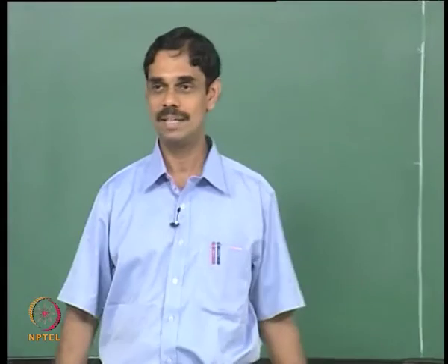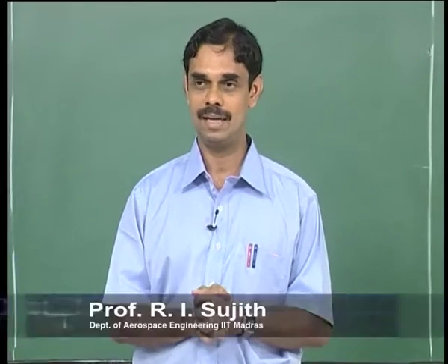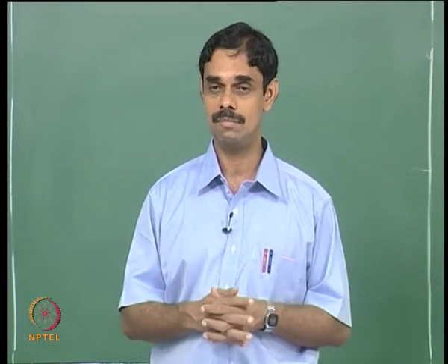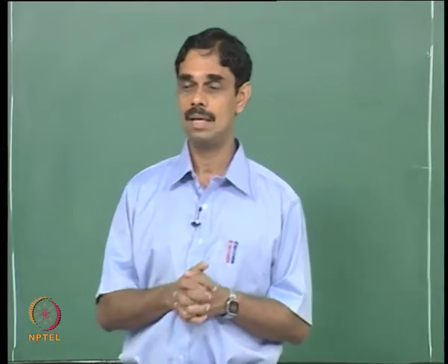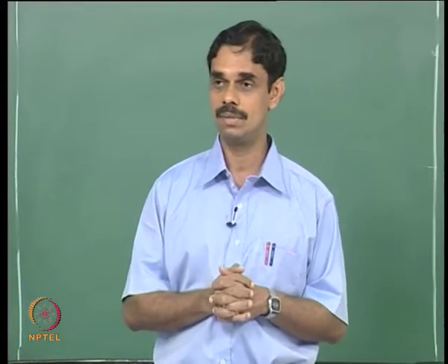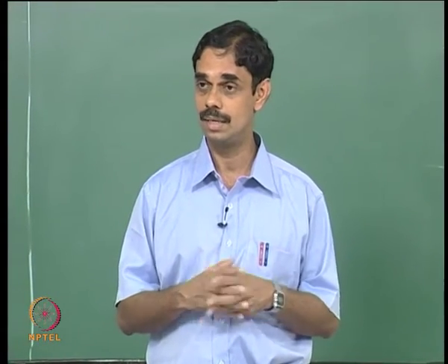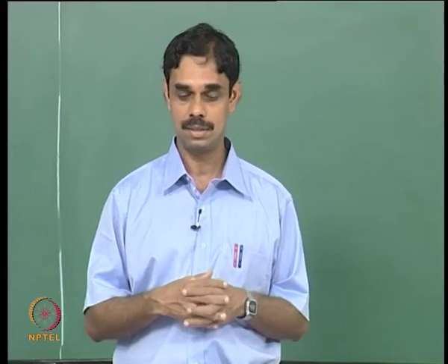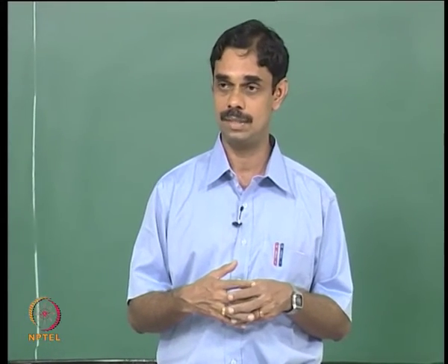Okay, good morning everybody. We were looking at this simple example where we had a heat source in a pipe, which was located at some location, and we looked at the heat source having an unsteady fluctuation, and we modeled the unsteady fluctuation in terms of the velocity fluctuations using the so-called Crocco n-tau model. This is a very famous classical model, and then we try to find the stability of the system.